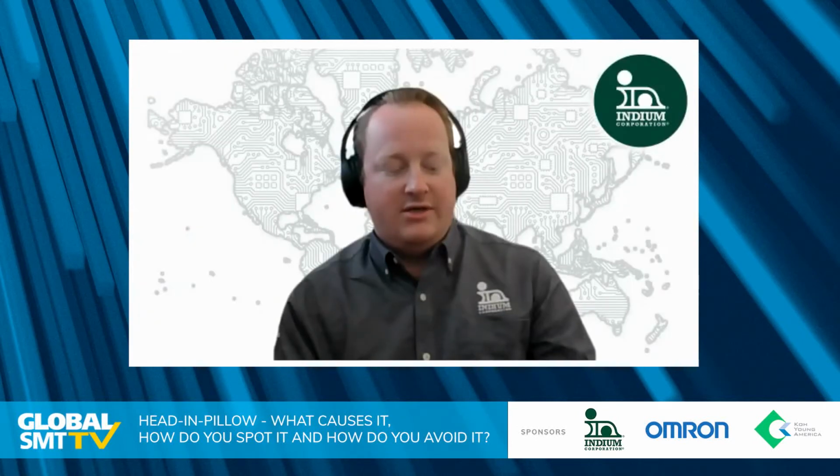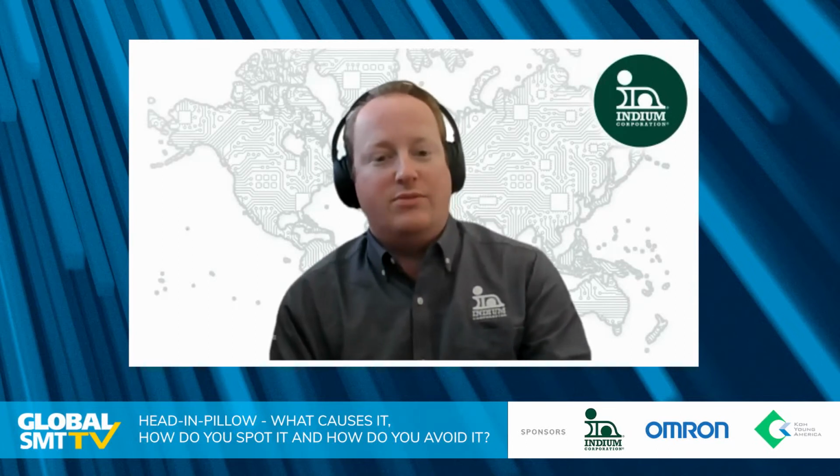Absolutely. Okay. So I think you probably answered my next question, which is are smaller devices more prone to warpage? I would have thought larger ones are actually. Yeah, definitely. But to add on to what Kevin mentioned about the head and pillow defect, the real cause, in my opinion, is more the oxidation, less the warpage.